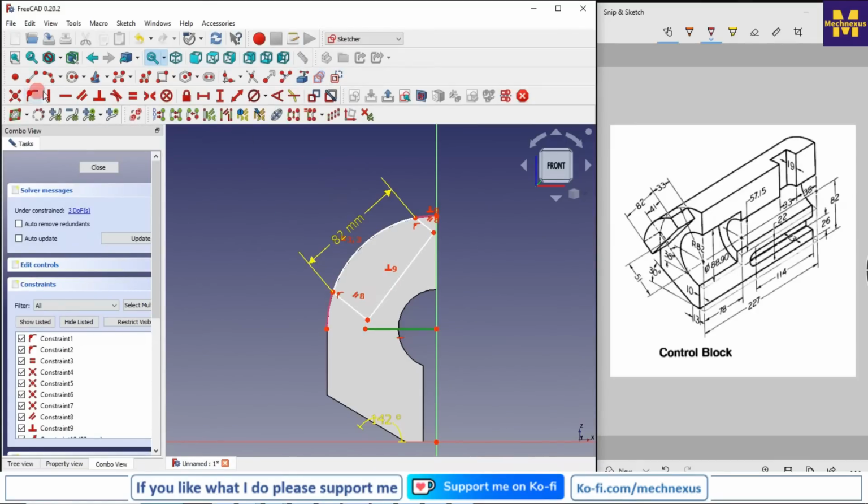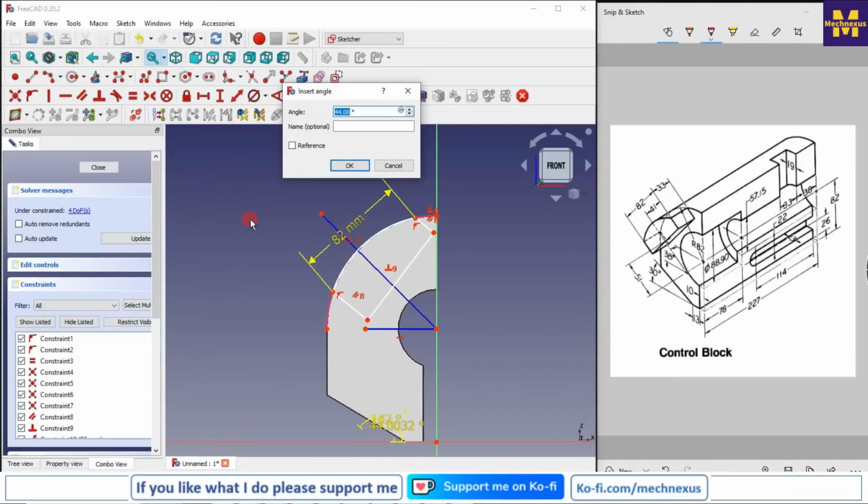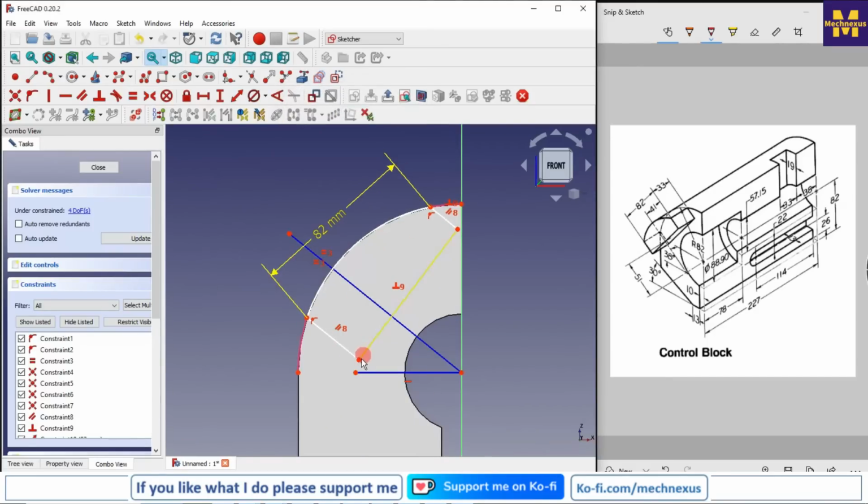I will draw the angle. Actually, if we see here, this 38° passing through the center here. Okay, so it would be symmetric to this. So for this we will draw a line at 38°. So I will select the line and I will make it construction, and I will give my angle 38. Okay, so now this would be symmetric and this would be perpendicular as well.